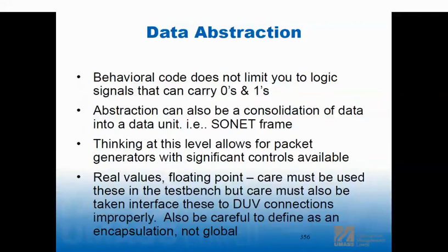Well, isn't that great? Because it took the burden off the test case until you wanted to put a bad CRC in. Oh, wait, the bus function model calculates the CRC automatically, and I want a bad one. So what you just did is you added another bit in the interface to the bus function model that says bad CRC. Okay, let's extend that a little bit.